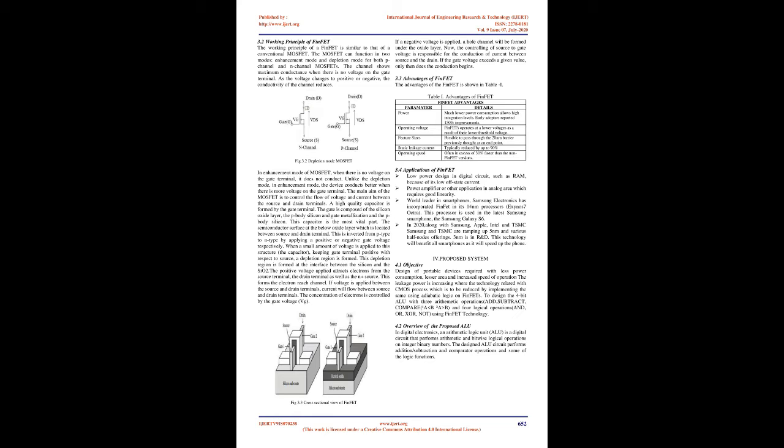But adiabatic circuits highly depend upon the power clock and parameter variations. In this paper, Pradipti et al. [7] designed and simulated a MUX and a 1-bit sum and carry adder on Cadence Virtuoso using 180nm technology. In the analysis, PFAL is compared with conventional CMOS logic on the basis of frequency and supply voltage. The proposed technique shows a reduction of power dissipation as compared to the conventional CMOS design style. The results analysis concludes that adiabatic logic can be used for the implementation of relatively large, complex circuits that dissipate less energy than conventional CMOS designs.